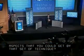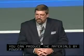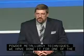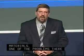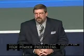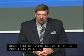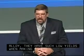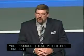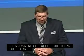Yeah, I'll start with the second question. You can produce these materials by powder metallurgical techniques. We've done it for one of the high temperature shape memory alloys, the nickel, titanium, palladium materials. One of the problems there is the yield for your powder processing. Your yield is probably about 50% of your original melt. So when you're working with these precious metal containing alloys, to have such low yields when making the powder is a major disadvantage, but you can produce these materials through conventional powder metallurgical techniques, and it works quite well for them. The first question, I don't quite understand what you're asking about in terms of the hysteresis of the strain.